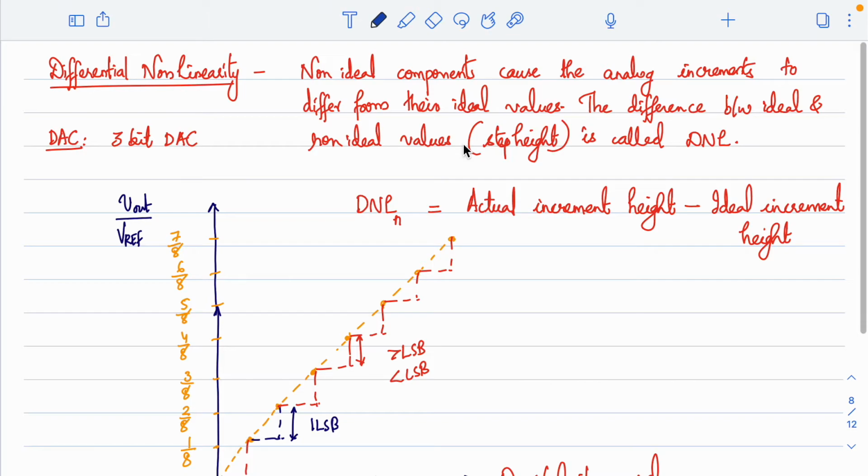Yeah. So for any DAC you can get the characteristics. You can compare the curve with the ideal curve. When I say ideal curve, for every bit change 1 LSB is what we need to look for. So what is the implication of this DNL? When you have the DNL value, what does it say about a DAC? We quantified this difference as differential nonlinearity corresponding to every bit. By looking at the DNL value, what can you infer about a DAC?